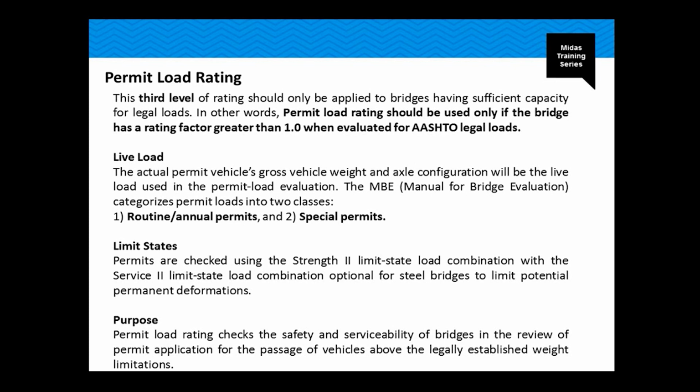Then we have the limit states. The permits are checked using the Strength II limit state load combination, with the Service II limit state load combination optional for steel bridges to limit the potential permanent deformations. The purpose of this permit load rating, as its name mentions, is to check the safety and serviceability of bridges in the review of a permit application for the passage of a vehicle above the legally established weight limitations. So basically, to give the check or the yes for a specific vehicle permit load.